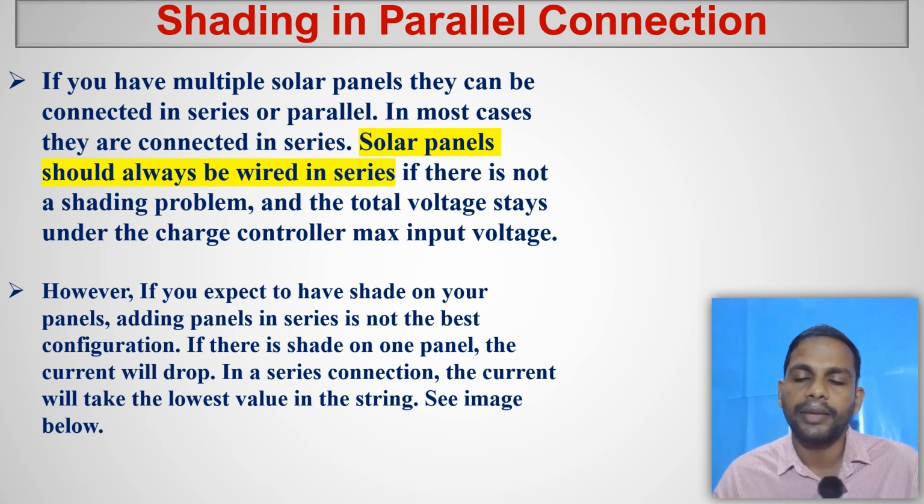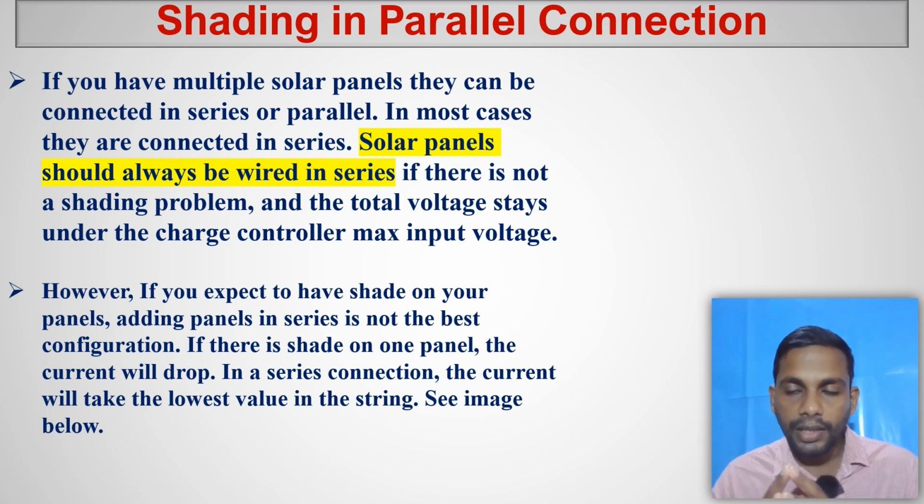Let's say you have a 20 volt system, then you need 6 amperes. Even if you go to a 50 volt system, you have like 2 point something amperes. So the idea here is, if you increase the voltage in the entire solar system, the output voltage, you can reduce the current, because P is equal to V into I.